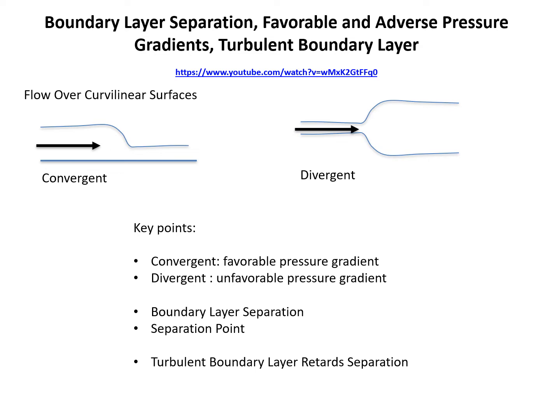You'll see the flow going through this narrowing of the tube, and you want to look on the bottom part of this to see what happens to that boundary layer. So spoiler alert, what happens when it moves into the smaller portion of that tube is that the fluid starts flowing faster and the boundary layer gets thinner.